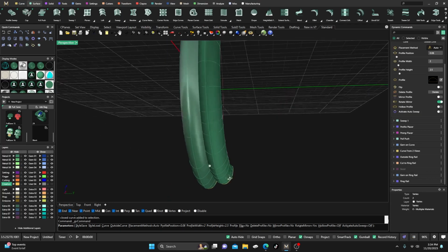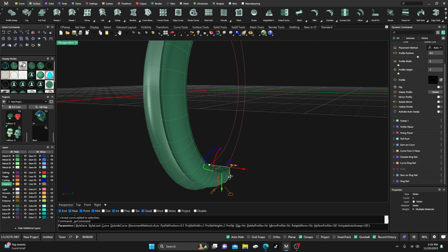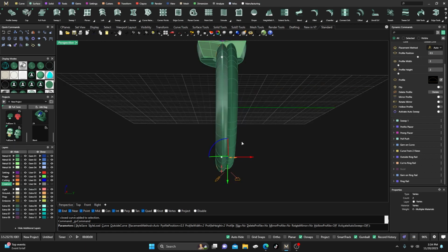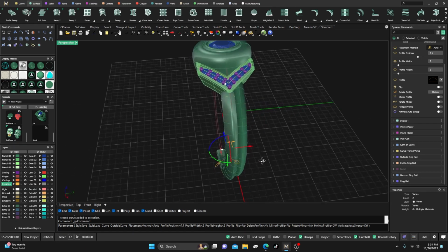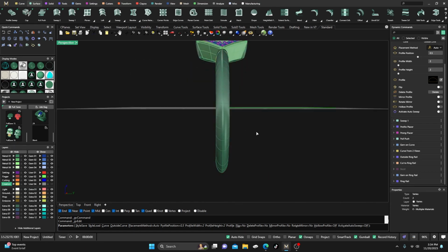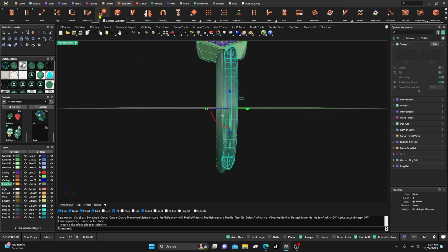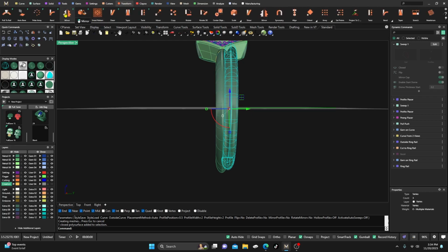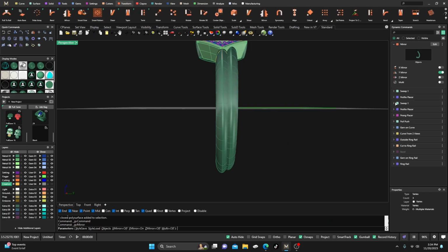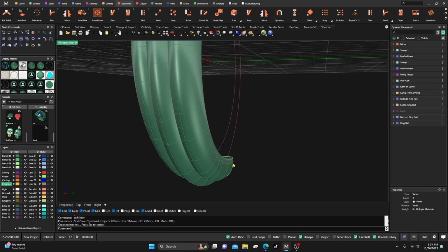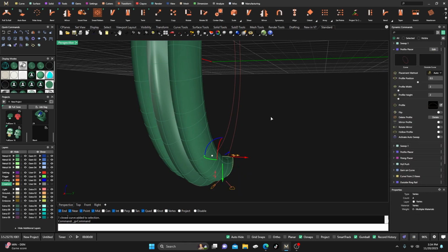And then this one down here, same thing. I think you have it tapered, so you want to bump that one in more, right? So that it kind of tapers down. So we got something like this. Let's go ahead and take that, and we'll go to transform and parametric mirror, over to our X direction, not our Y. Hit enter, and now you can go back and make final adjustments on everything if you want it more tapered, right?